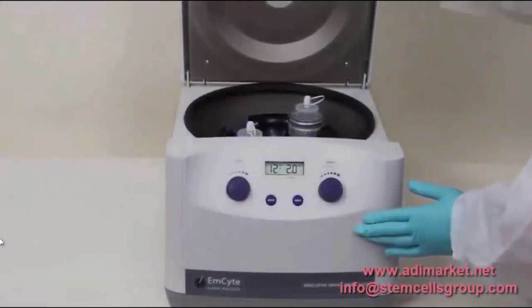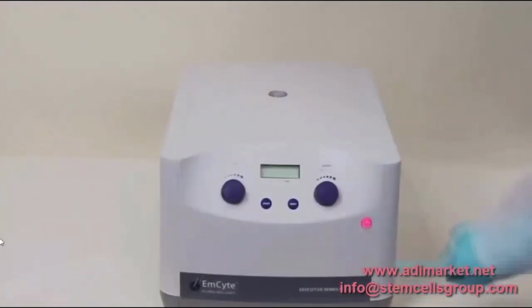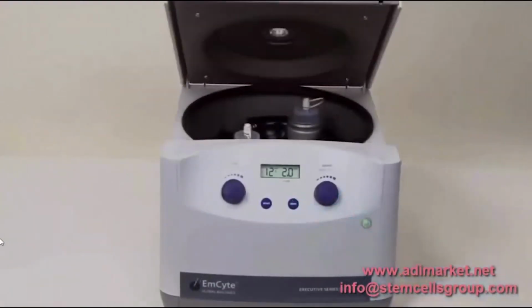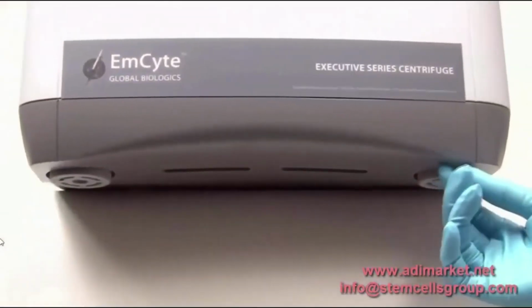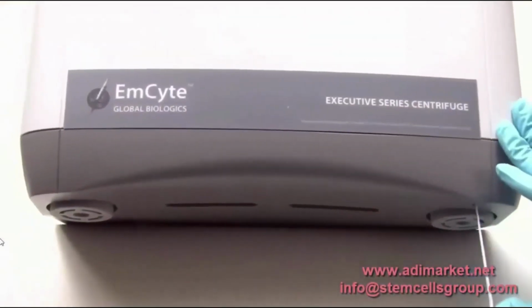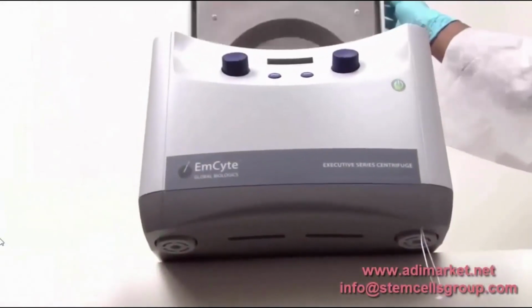This machine has an automatic lock and release function for lid operation. To open the lid, power up the machine and press the open button. You can manually open the lid without AC power by releasing the pull string at the base of the machine, where you can pull it to open. The lid automatically locks when closed.